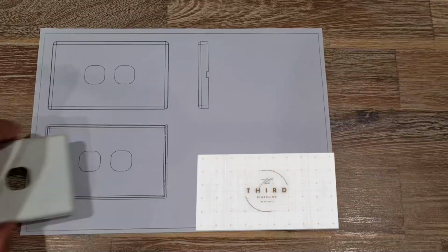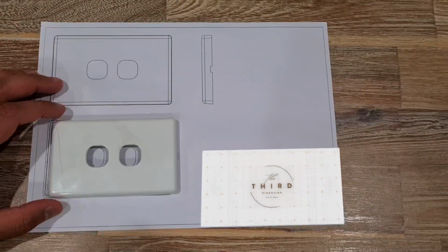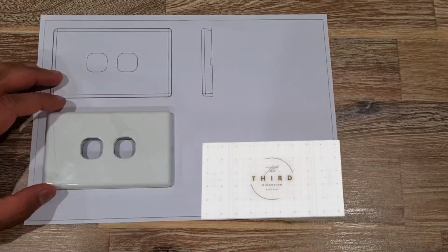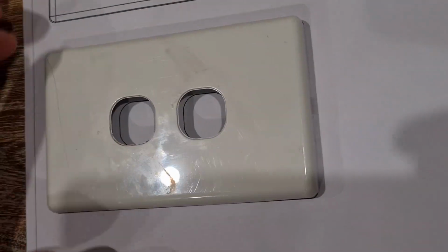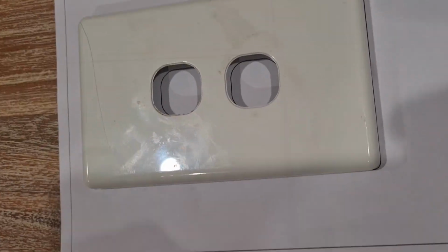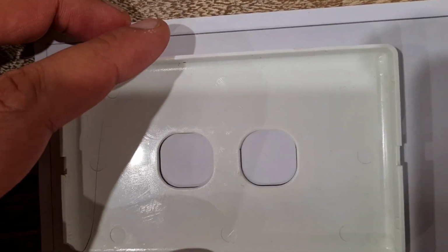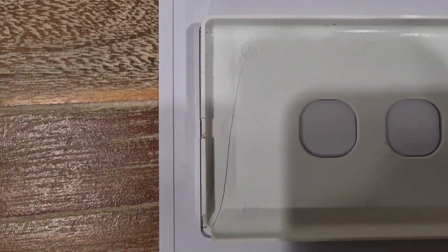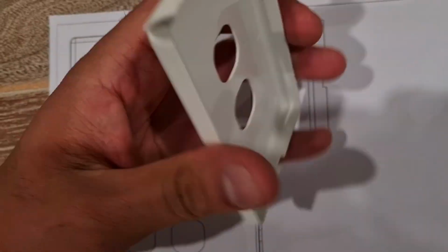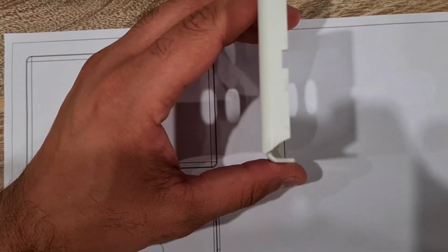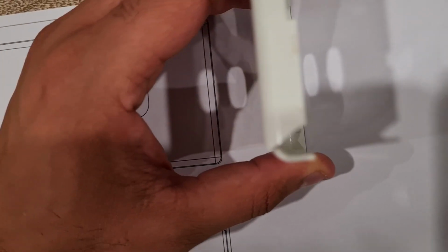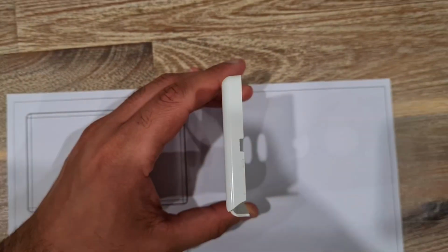I used the same method in my project, and I used the full scale method. Here you can see I have made the model and taken the printout at 1:1 scale, which is full scale, and I am verifying all the dimensions against the broken switch cover, just to make sure that all my dimensions, thicknesses, folds, and fillets are similar to the already broken switch cover. My very next step is to print it using my 3D printer.